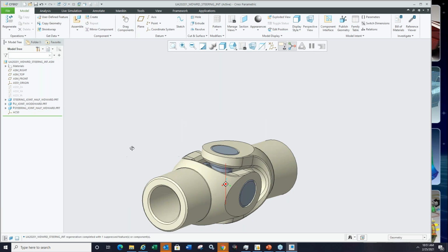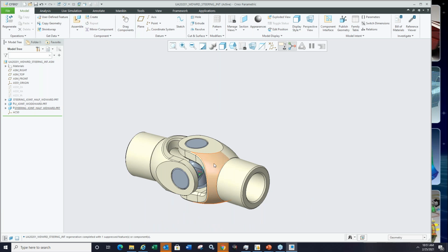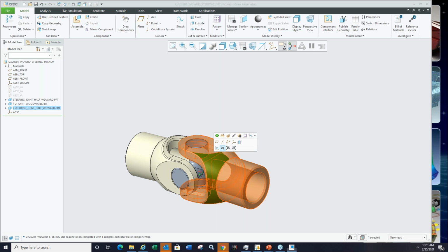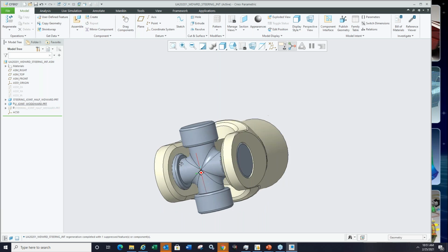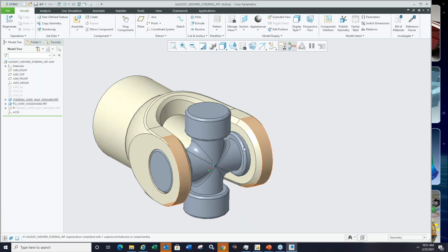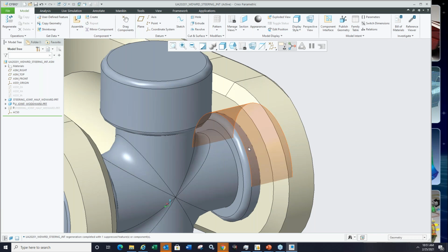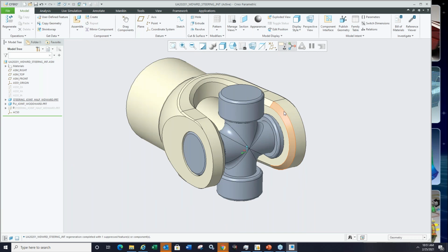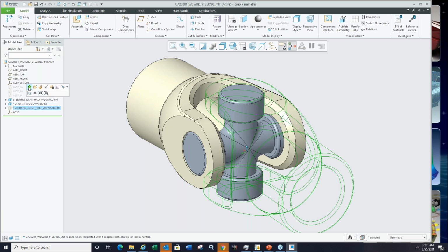Pretty straightforward assembly. Now, in the case of a component on an assembly like this, I may want to control the degrees of freedom between this cylindrical surface and the hole, right? Is that going to be a hinge? Is it going to be fixed? How is that going to behave, right? When I apply, for example, a torque and I fix it at one end, this is when you could take advantage of it.